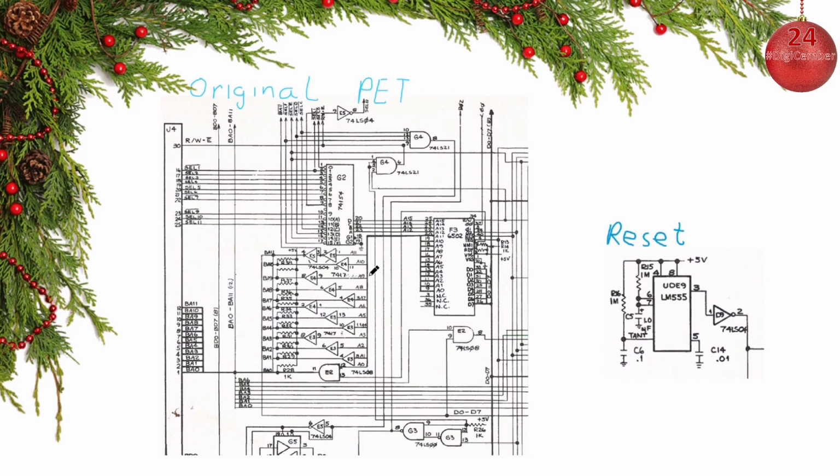You can grossly say that they have put buffers on all the address lines. And they also tie them high and use chips with ordinary logic. It's a 7404. So this is probably to make them more immune to noise. And you also have on this one some trickery with the read-write signal and the Phi2 clock.